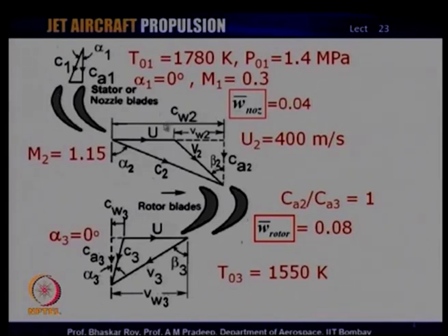So, in aircraft gas turbines, we still keep the V2 value subsonic. This is deliberate and done very consciously for the turbine design, so that the losses through these turbines are somewhat under control. As you can see, the loss in the rotor is already a little on the higher side, and through the shocks it would have gone even higher, and hence most of the aircraft gas turbines even today are essentially subsonic rotors.